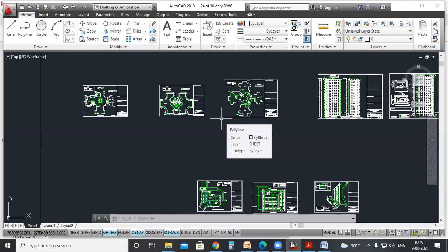But as I said, if you provide lightning protection for the building, it is actually only protecting against lightning strikes coming to your building. Okay, you cannot give protection to the equipments inside the building since they are vulnerable to the surge current coming through the electrical lines, electrical cables. So for that, we have to provide surge protective devices. Whenever you do a project, you can recommend both the surge protective device and lightning arrestors. Okay, is that clear? I can show you some catalogs on surge protective devices.